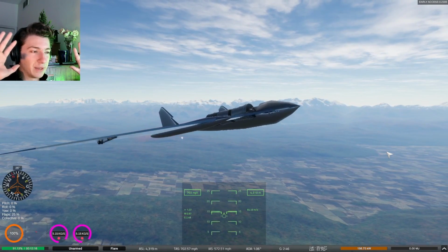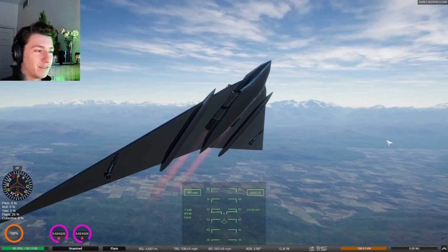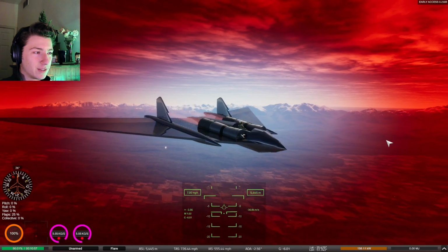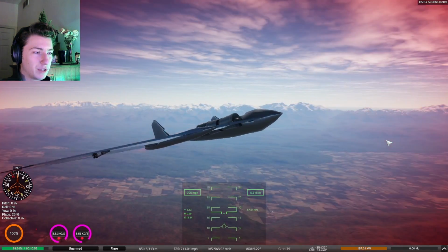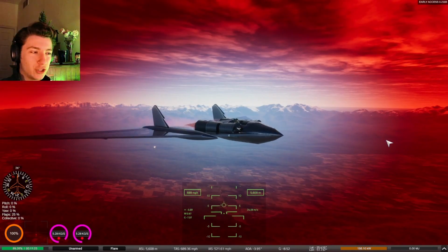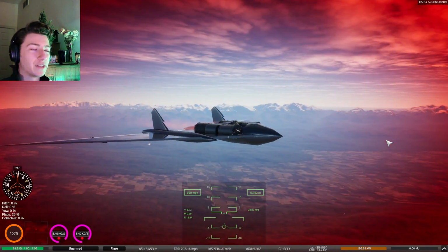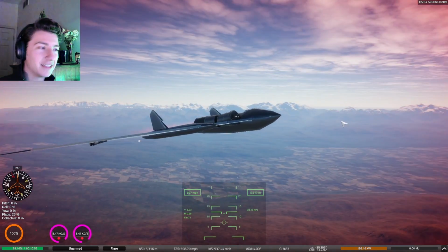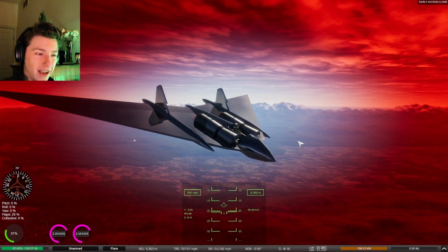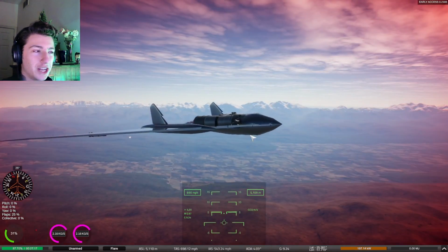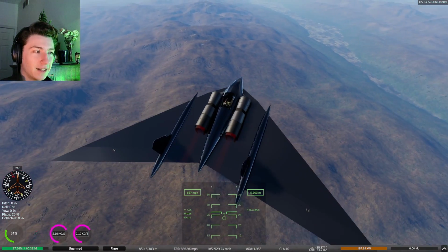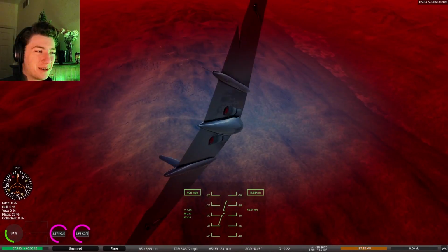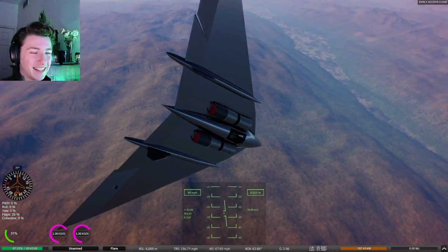You'll see what happens very quickly. So we start to go up, and then if I steer down into it, we start to pitch down, pitch up, we get this sort of oscillation going that actually prevents the plane from going supersonic and staying stable. The exact science behind this is a little bit complicated. It has to do with the fact that the center of pressure changes its location when you go supersonic. So you have to really tune the fly-by-wire system well to get a supersonic craft to function properly.